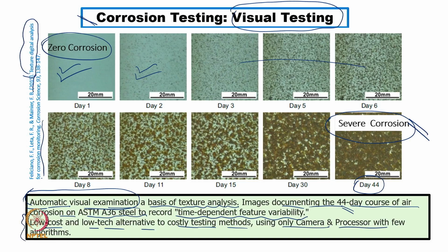So, this process is important to understand. Overall it really helps the material scientist, the metallurgist, and the mechanical engineer to predict well in advance by understanding this kind of phenomenon. And if we are able to analyze the surface texture, then visual testing is also very helpful, which is cost economic, less costly, or maybe even low tech also. We do not really require training, because even with radiography, the technology is a little in depth, we need to understand it, it takes time, and it really requires skills to operate.